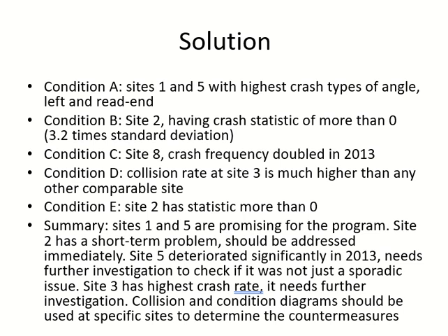These two sites have a problem with rear-end collisions and angle collisions and so on, and the other sites I already mentioned. On these two sites we will definitely change the lights because it has the highest impact here. Site 2 may have a short-term problem because it has only been open for 1 year. It should be addressed immediately because it has just opened and there have been so many crashes. Whatever the problem is, it is very urgent, so it should be done immediately.